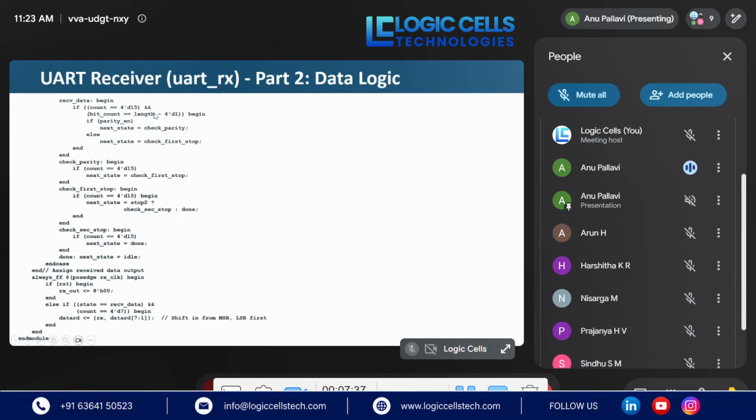This is the second part of the receiver. The receiver continues processing the received frame. In the receiving data state, it waits until the required number of data bits have been received. If the parity is enabled, it moves to the parity checking state. Otherwise, it directly goes to the first stop. Then, if two stop bits are selected, it also checks the second stop, and finally the receiver enters the done state. And here it assigns the receiver data output, and it clears the received output during the reset, and it shifts the received serial data bit into the data register.